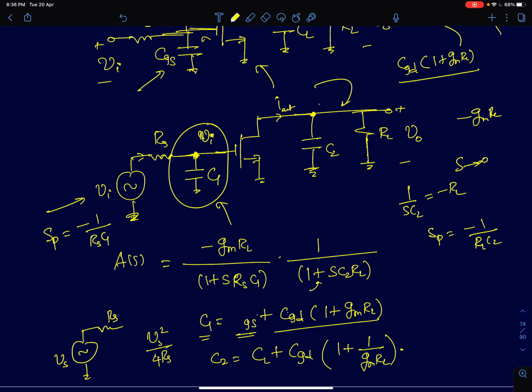And we can see because there are capacitances at both these nodes, at infinite frequency, at omega equal to infinity or s equal to infinity, capacitors offer 0 impedance. At that condition, both these nodes will go to 0. So therefore, we can say there are two zeros in the system and both these zeros happen to be at s equal to infinity. So since they are not finite zeros, we won't be showing them on the transfer function.